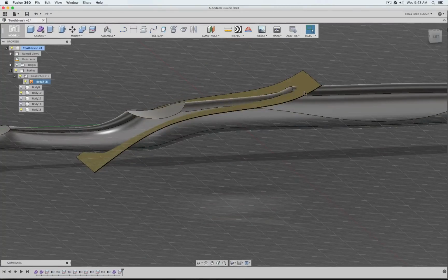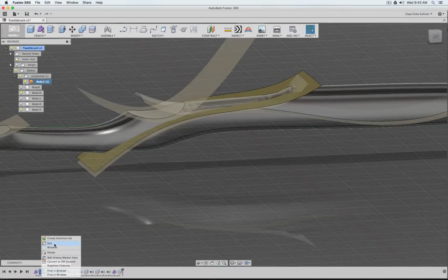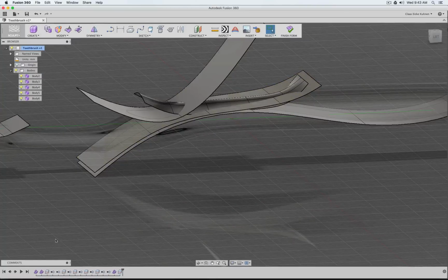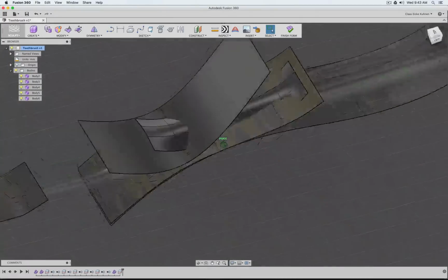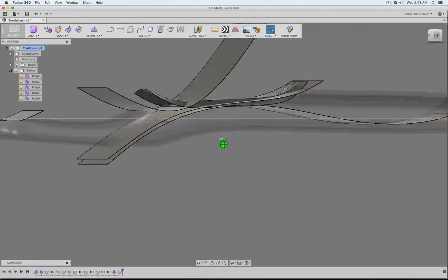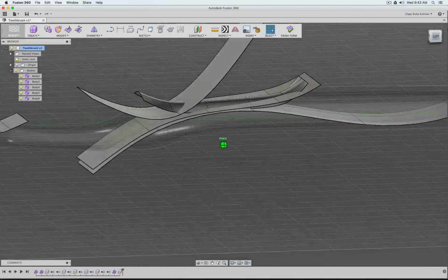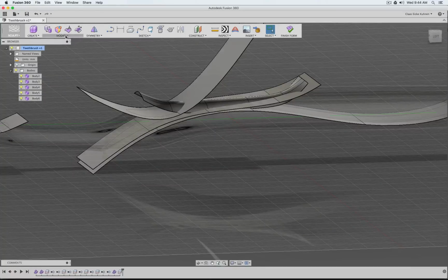I could also have modeled this one in Blender with the sub-D modifier nice and smooth, but that would have added more geometry points, made it maybe slower. So I work with more of a linear mesh. And to turn something that is smooth in T-spline to be linear, we can use the Crease command.